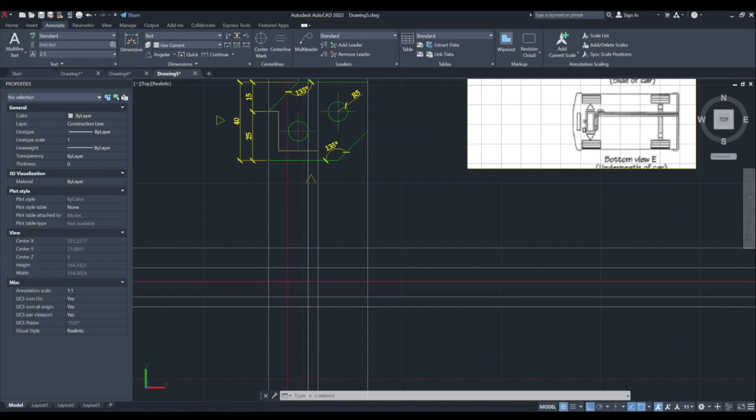tracing the line. So let's, using our imagination here and some logical projection in our mind, let's say I will create a polyline, but now I will use the layer. So again, create a layer and then create a solid line, double click, and this is now the current layer. Now command polyline P, trace the object like this, and then here, and then here, and then here, next point, and then close command.